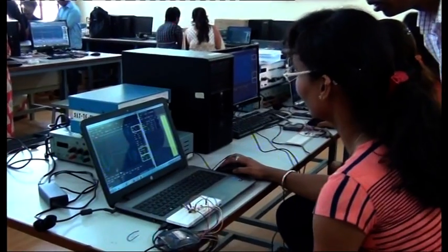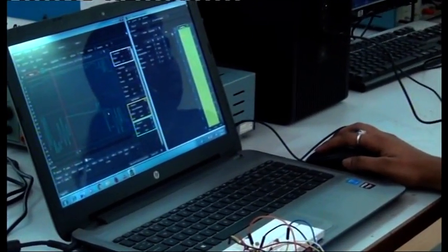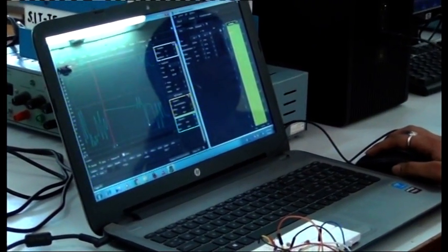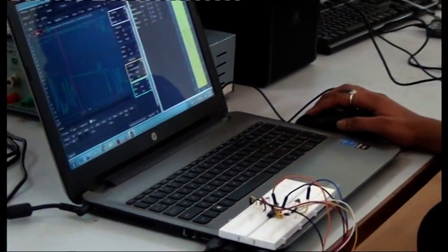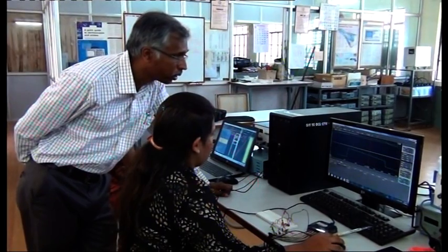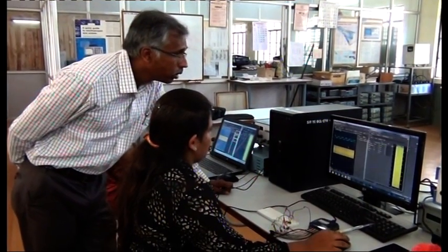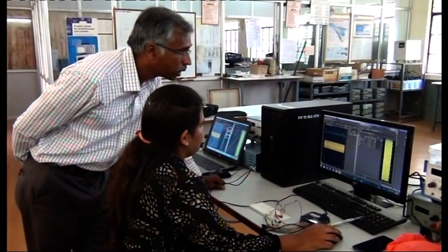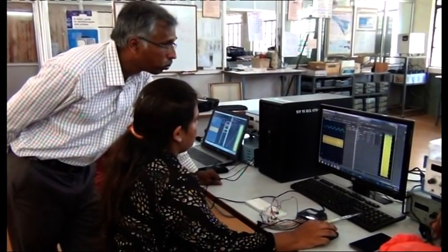It goes up to almost 200 kilohertz. So it will capture frequencies from 112 to almost 200 kilohertz. Can you show modulation of the FM signal? So this is your FM signal, and the carrier frequency is 70 kilohertz.